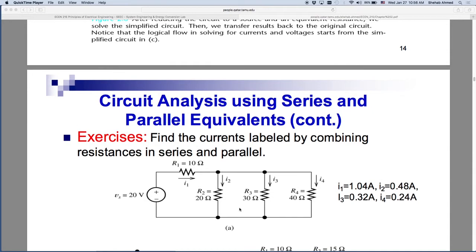There's another way to help speed this up. The logic is the same and the proof will be the same, but we will introduce some rules that will help you do this a bit quicker in this class. So if, for example, we knew what I1 current was, we will come up with a rule called the current divider rule.